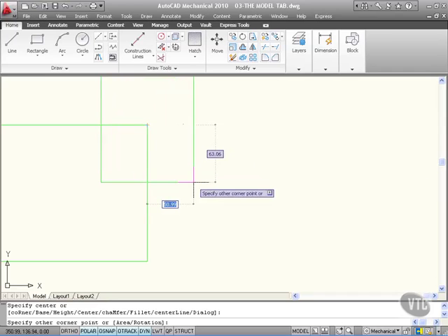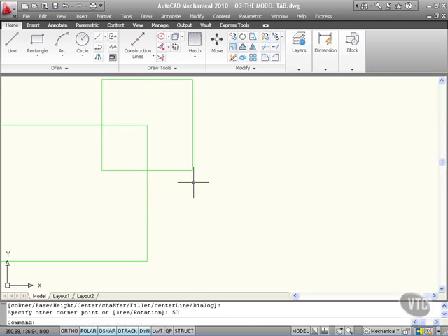I can type the distances in the boxes. So in the X direction that's highlighted there, 50.99, I actually want that to be 50 from the center. I then press the Tab key on the keyboard. And I also want it to be 50 vertically from the center, so I type in 50 there, and I press enter again. And as you can see there now, I have a rectangle with equal sides, in other words, a square, and that is actually 100 this way, remember, and 100 this way, because I've gone from the center, 50 along that way, and 50 down that way.